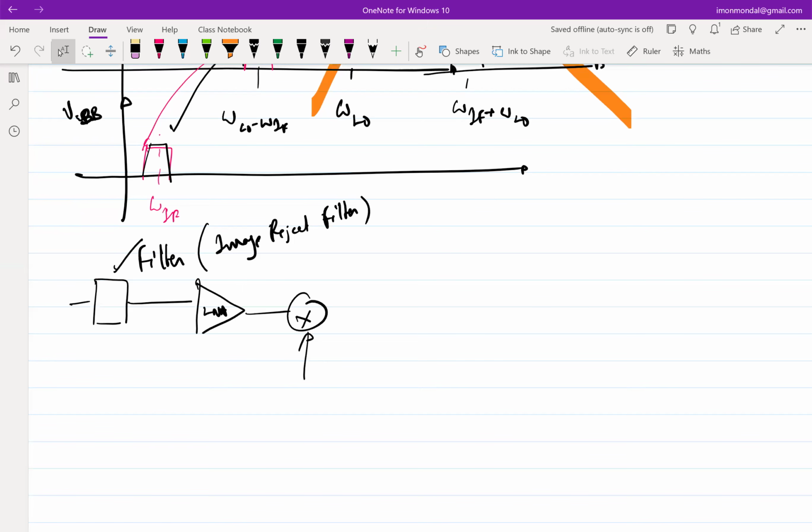So the effective noise figure of the signal chain can degrade. Those are the two negatives. I agree, perfectly valid negatives. But is there any positive at all of adding this before the LNA?